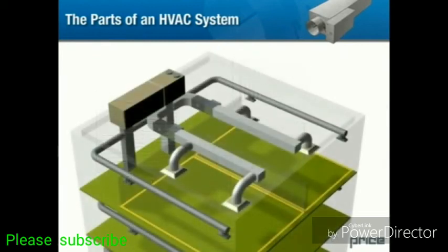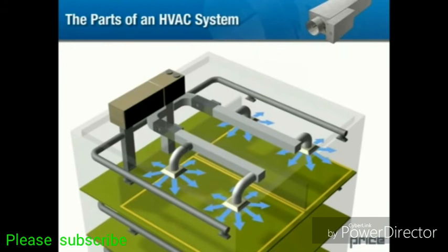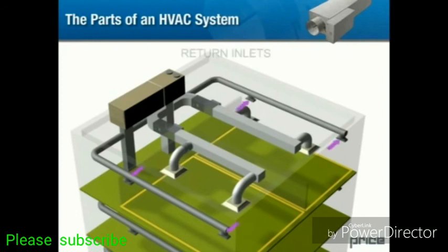The diffuser's job is to direct the airflow throughout the occupied space in the most efficient manner possible. More information on desirable air patterns is provided in the Space Air Diffusion section. We will discuss diffusers in more detail in air outlet selection. Once air enters a space, where does it go? Air circulates through the return inlets and returns to the air handling unit.